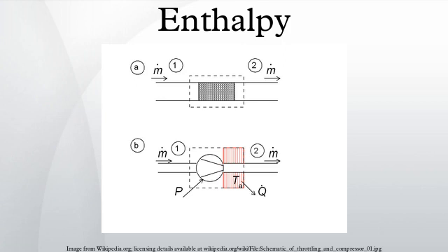The first law for open systems is given by: where the first term is the average internal energy entering the system and the second is the average internal energy leaving the system. The region of space enclosed by open system boundaries is usually called a control volume, and it may or may not correspond to physical walls.